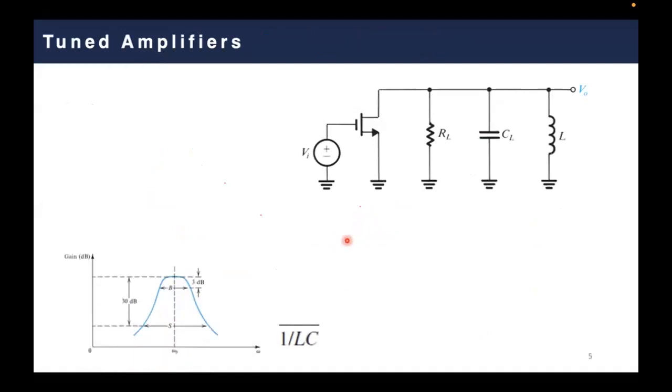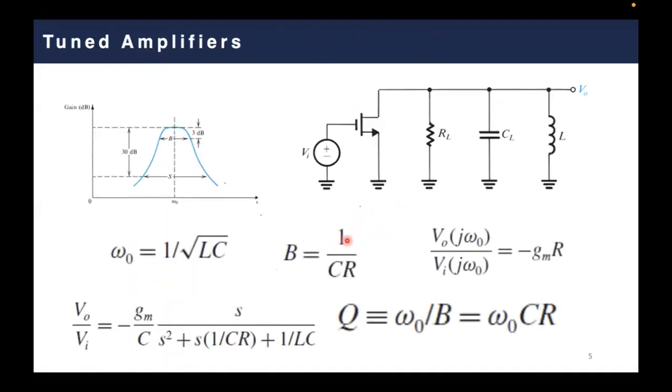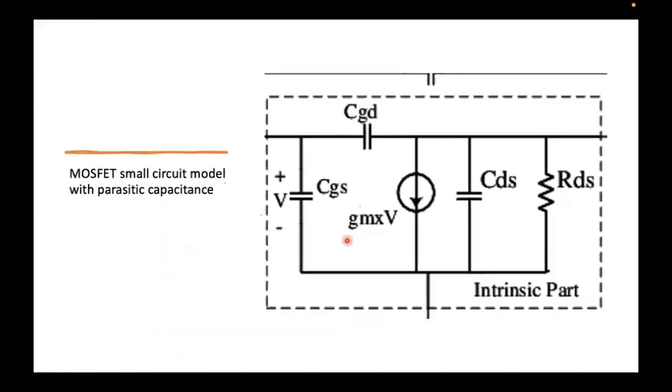However, with applying the parasitic capacitance impact on your circuit, then you should start to have this CGD impact, or gate drain impact. This is a very major effect for the parasitic capacitance, because simply this capacitance is feeding back the output to the input, making this a connection that must be considered.